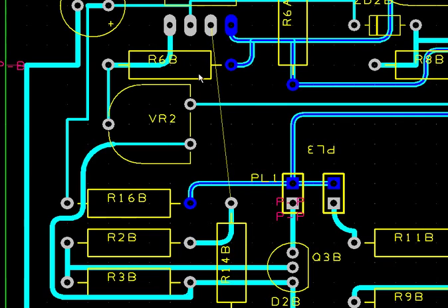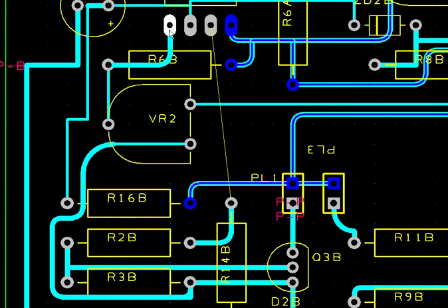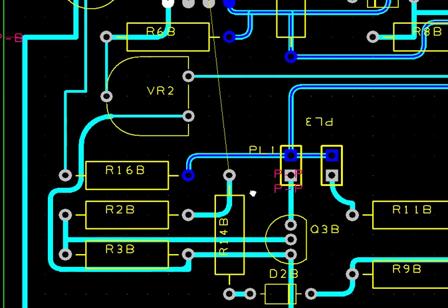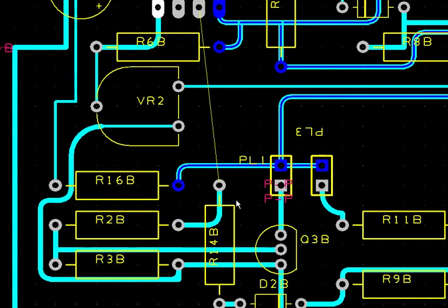Let me move this track a minute to route that again. Sometimes it will route a different path. And I can draw them in manually, but it's a lot tidier if you can use the auto routing thing. You just right click for the auto route. Alright, we can get through there, but manually it's going to be just fiddly.